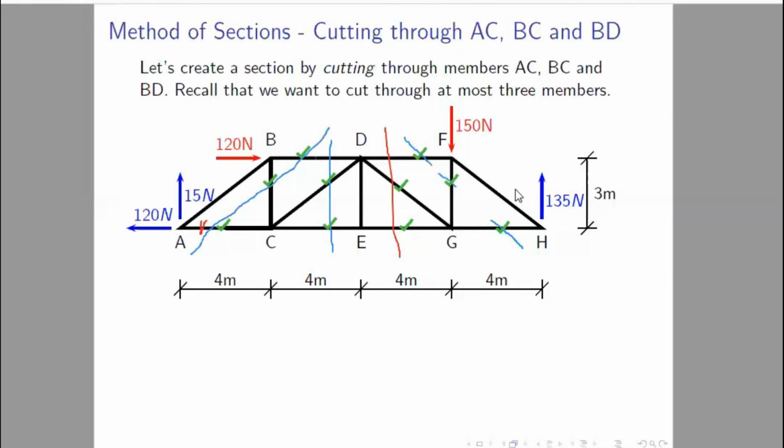So we can also solve these three unknown forces just by taking another section here. If we cut a section here, you can see this is very similar to method of joints. If we cut a section using this, taking the right hand side, we can easily find the unknown member force FGH, and this is very similar to method of joints. You already have learned this. And if we cut a section here, we can easily solve for member force AB, and this is also very similar to method of joints. So this is very easy for you to solve.